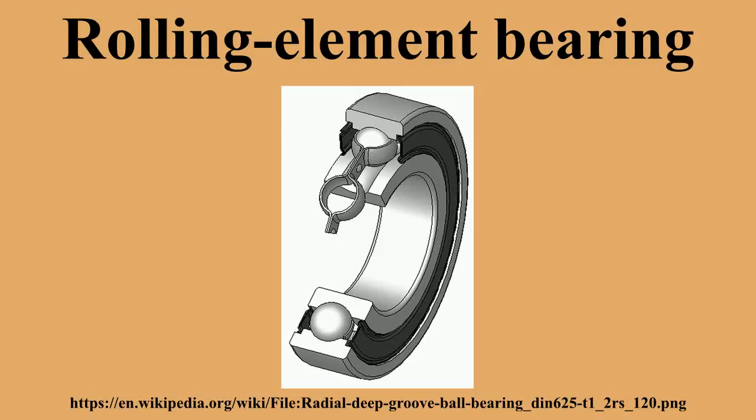Note also that the deformed ball and race do not roll entirely smoothly because different parts of the ball are moving at different speeds as it rolls. Thus, there are opposing forces and sliding motions at each ball-race contact. Overall, these cause bearing drag.